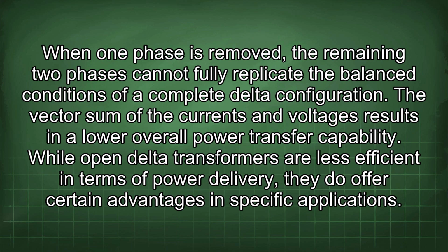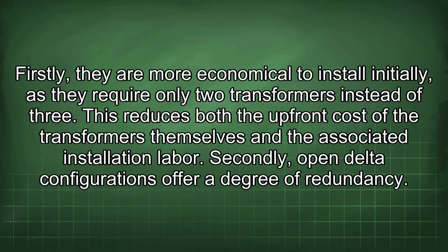While open delta transformers are less efficient in terms of power delivery, they do offer certain advantages in specific applications. Firstly, they are more economical to install initially, as they require only two transformers instead of three. This reduces both the upfront cost of the transformers themselves and the associated installation labor.